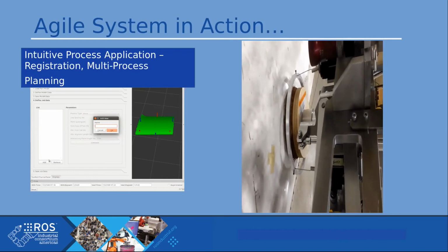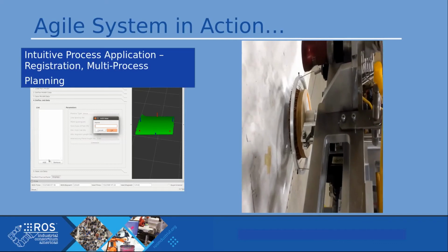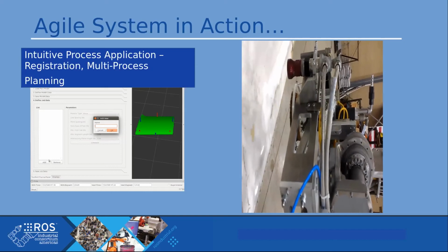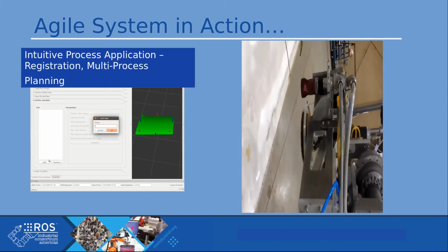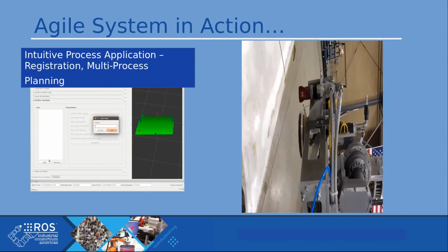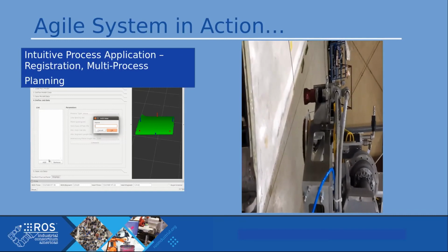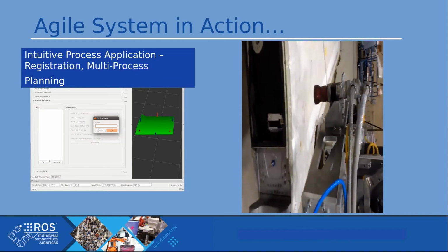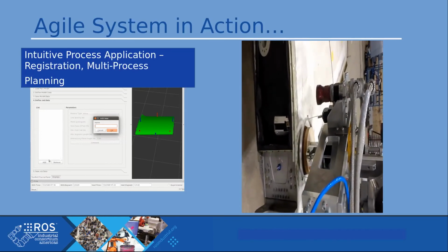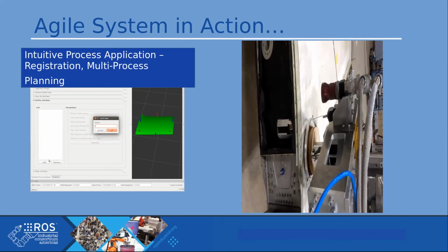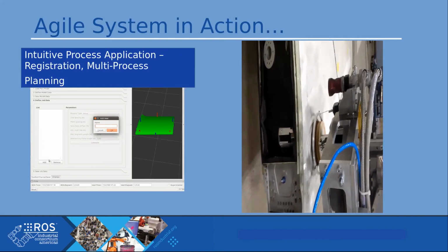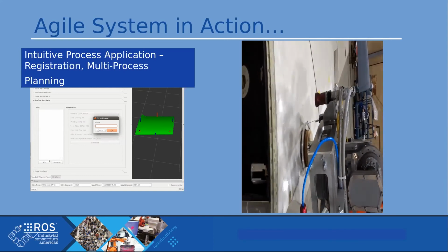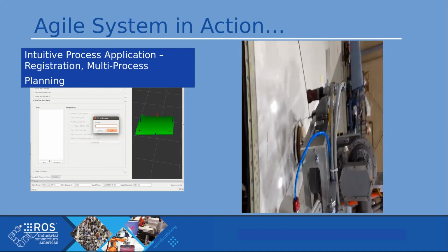We have some ideas that it'd be nice to update the URDF to handle some of these things that are easily done on industrial manipulators, where, on Fanuc, they can use DCS constraints to limit joint regions based on other joint values and those types of things. So we've come up with a pretty good way of handling that in TrajOpt by defining those constraints. Our next step is to figure out how or where we should put those. Should those be integrated into the URDF or, say, SDF, things like that.